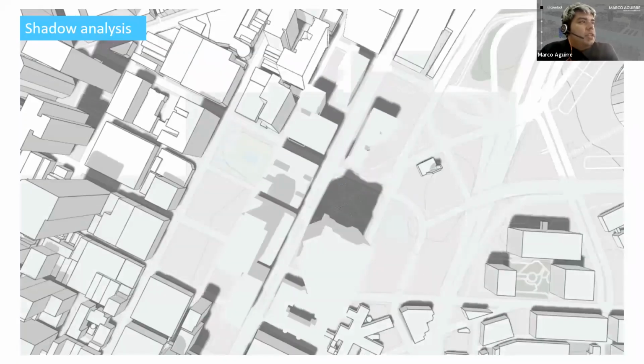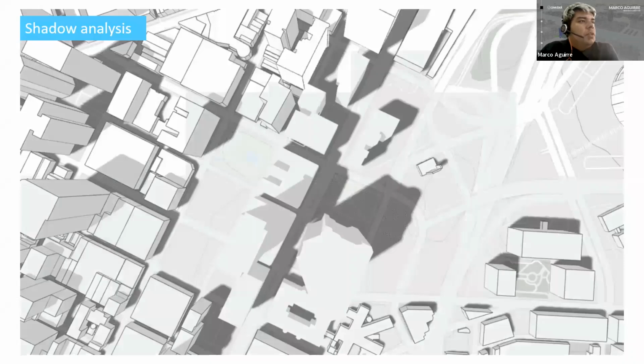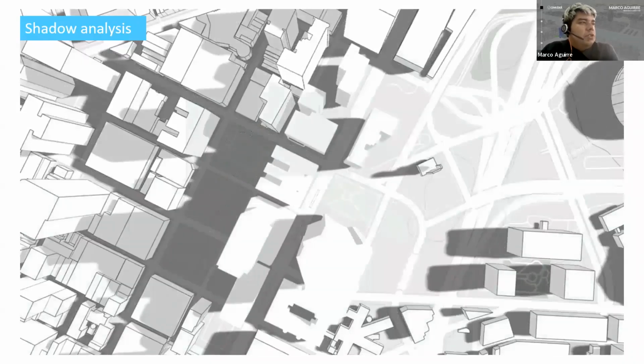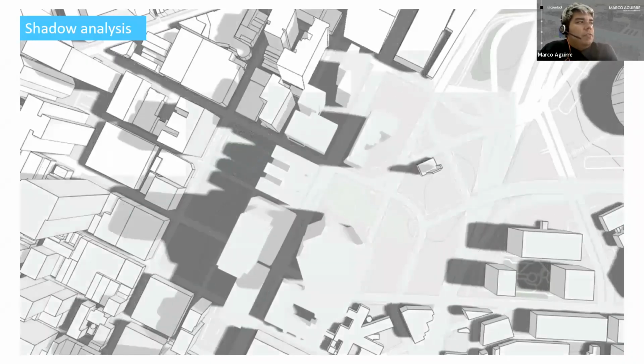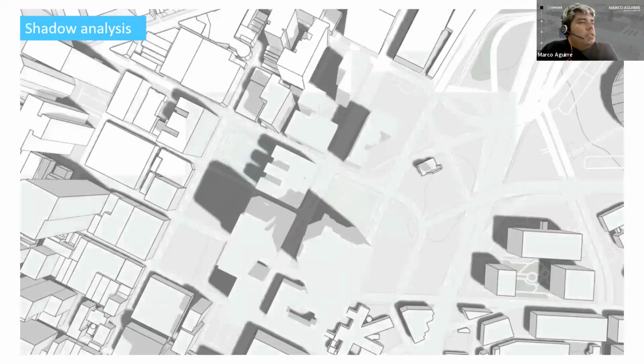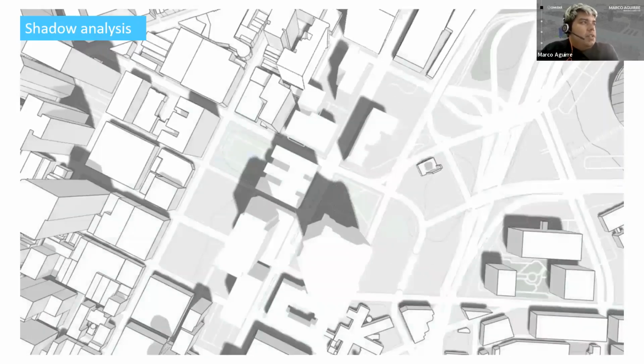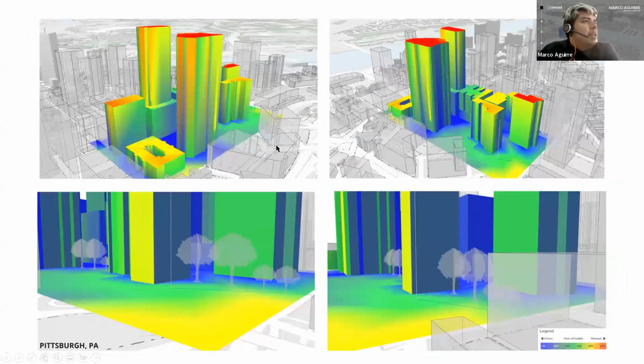Here's the shadow study. The building massings were already determined, but we're just trying to establish other information that would be helpful to inform the rest of the design process. Here you can see the sun hours analysis and also a quick street level site study, looking at tree distribution, what that's going to do at the eye level down here.